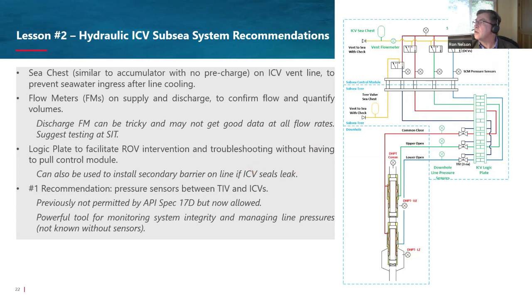Another thing you want to add to your subsea system, if you can, to improve the operability of your intelligent completion, are flow meters. Definitely on the supply side, and I know at least one of the vendors really promotes these on the vent side. These actually confirm that you have flow going to your ICVs when you're shifting them, and actually allow you to record the volume required for each shift over time, which can be a really important diagnostic tool.